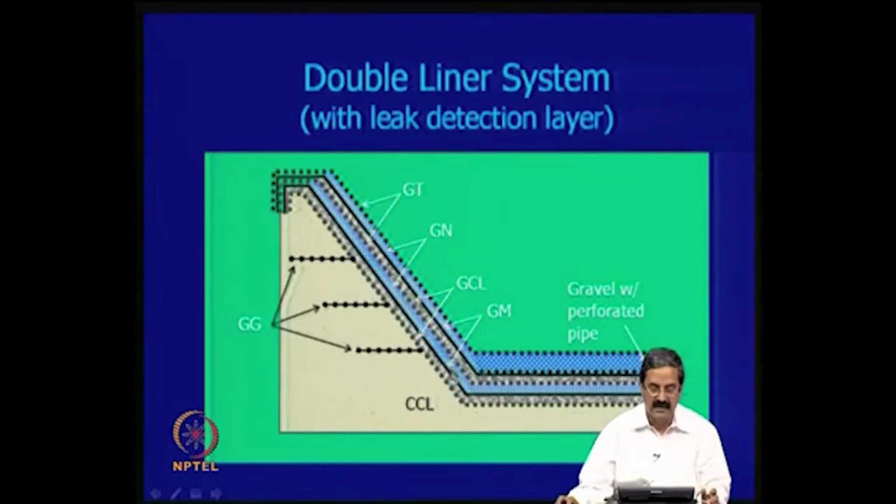And see, the thing is that you have all these materials, and geogrids are also there. As I just said, the slope is about 26 degrees, and if you want more than 26 degrees you can't have it. This is a 45 degree slope, and you can have it with geogrids like this and then increase the factor of safety to whatever you want.